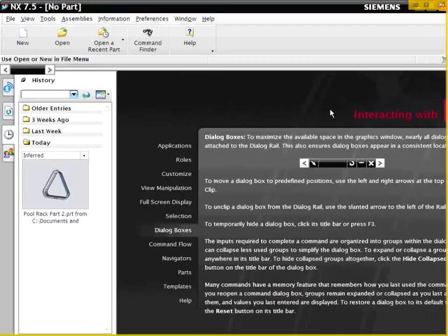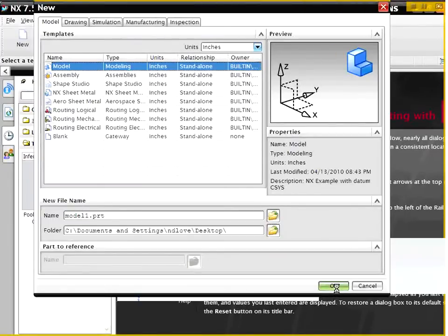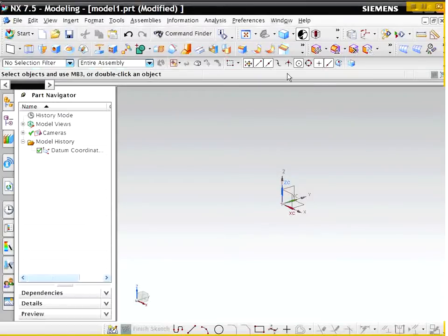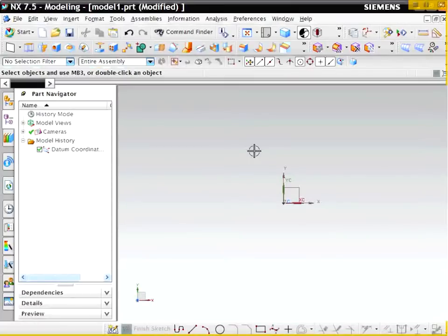So for example, when we start our sketch, we use the XY plane. What happens if we want to use something that's not necessarily on the XY plane or the XZ plane or the YZ plane? Well, what do we need to do? This is going to help us define different planes along different axes that are located anywhere that we define. It's going to help us draw sketches in different parts at different locations.